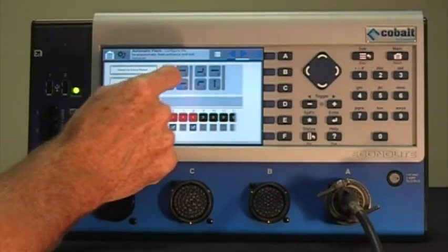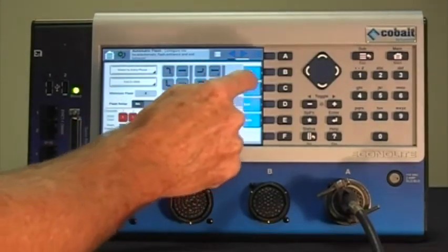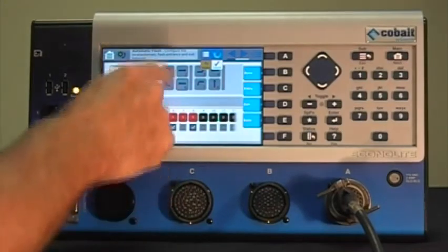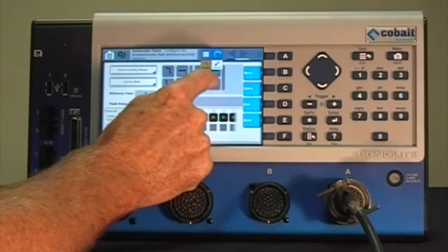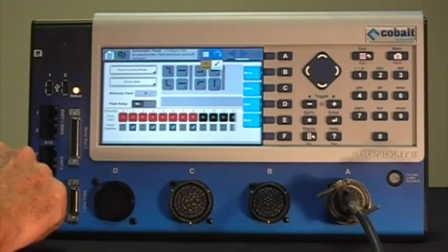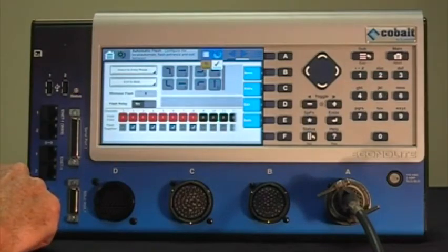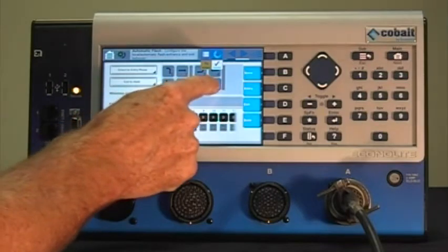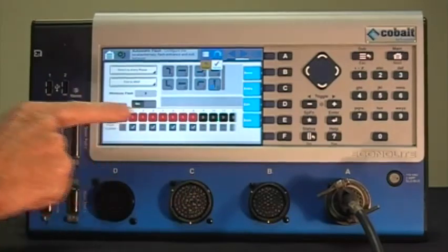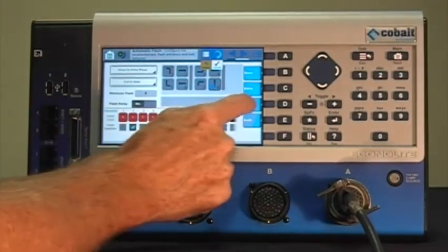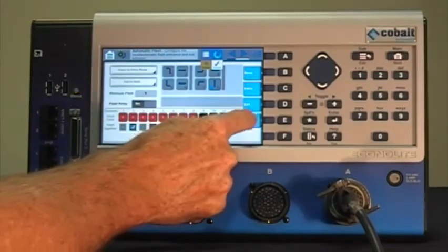So the first thing let's do is remove these assignments to 2 and 6. So I'll hit none on 2 and 6. And again, that message will come up, but I can just ignore that for now and keep on making changes. We wanted phase 8 to be the phase that it completes before it goes into flash, and it's the first one that it goes into after it comes out of flash. So when I highlight that, you'll notice that we can have none. We can have entry. This icon shows an arrow going into the flash, an exit, which is the flash, and then an arrow coming out, meaning it's coming into this phase, or both.